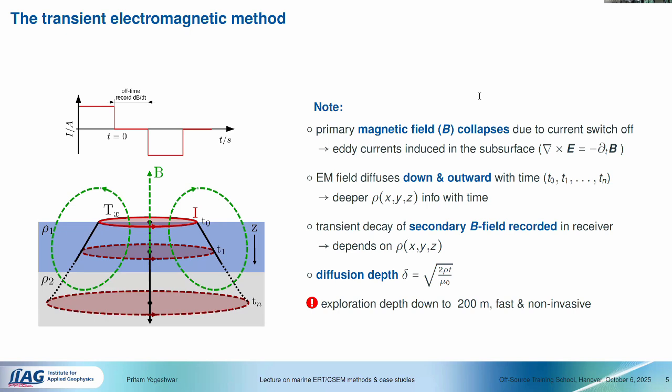So if you're working in a coastal setting and you're interested in finding out where your freshwater recharge is, how deep your saltwater intrusion is, then you can easily take this method and move along the coast and find the pathways where there's possible saltwater intrusion, where there's freshwater discharge. No? So you can just move along the coast with that, but don't expect greater investigation depth than maybe 40, 50 meter, no? But you should for sure be able to resolve the top of your saltwater intrusion. And you would see also how it varies along a coast. So for that, the method is very powerful.